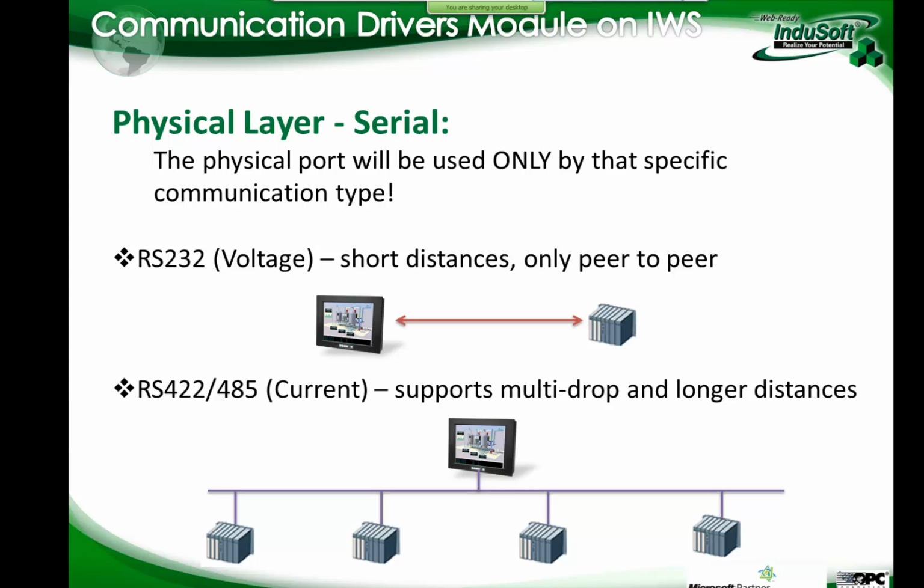And keep in mind that when you're talking serial communication, we send messages to the PLC to read the different addresses, one message at a time. So let's say I'm going to read the inputs from 1 to 64, and then I'm going to read the inputs from 65 to 127, and then I'm going to read the internal registers from 1000 to 1064, and so on and so forth. So the communication happens synchronously, okay? And so if you need to talk to multiple devices, RS-232 is not an option. You've got to go through RS-422 or RS-485.